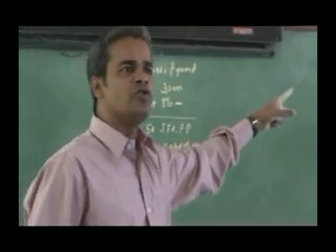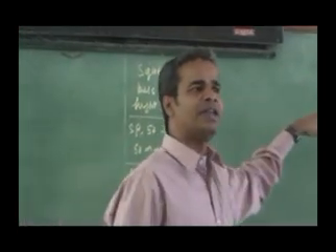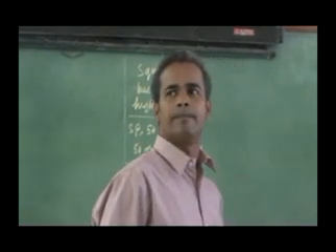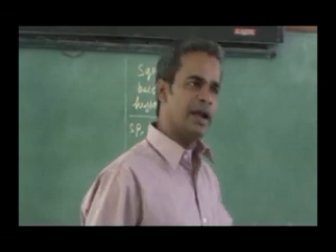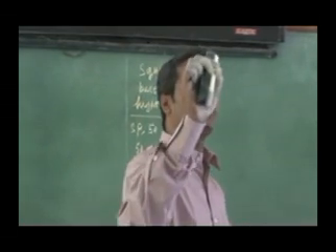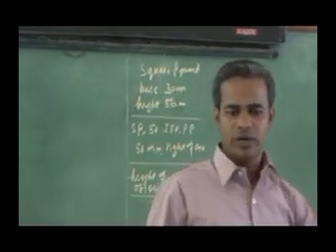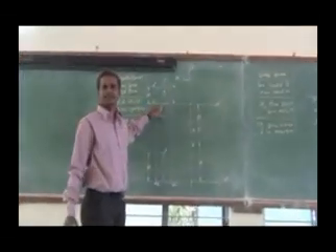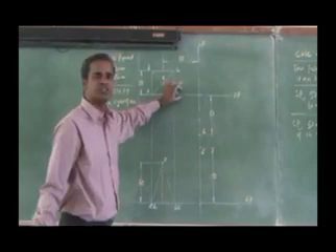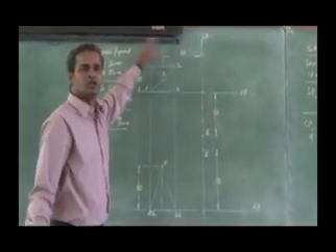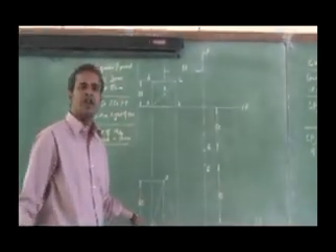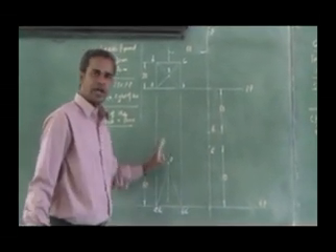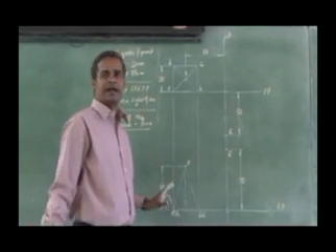The top view will be a square with slant edges. What will be the front view of the pyramid? A triangle. You have to get the perspective location of the apex also. Do it, make it fast. An edge is touching the picture plane, so the top view will be like this. The behind distance is 0. The edge is touching. So I have drawn the top view. I have drawn the front view for the height 50. It will be a triangle.